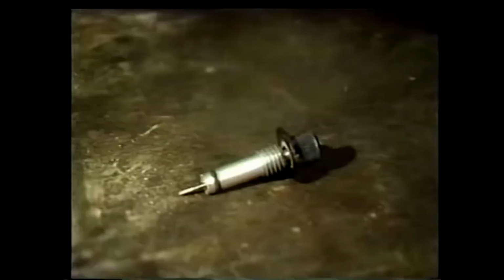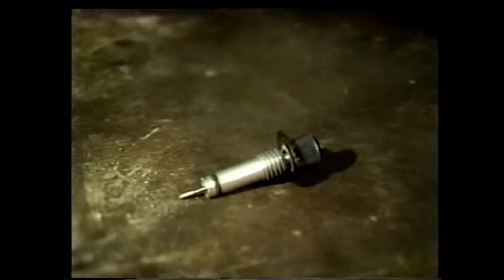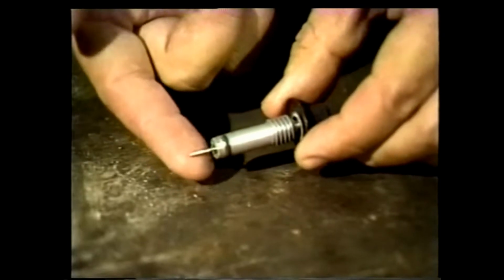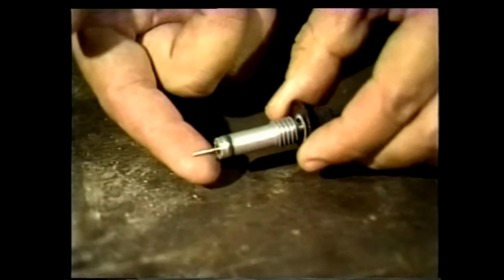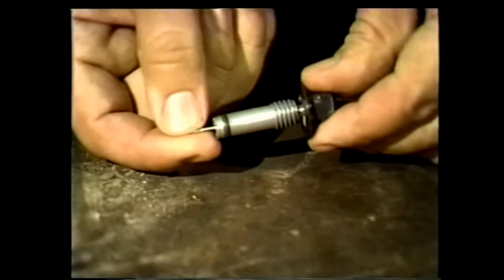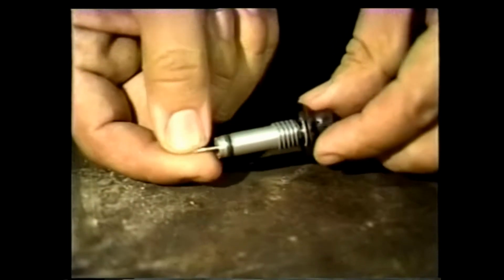The plug type disc has a wide seating surface. Now, this kind of globe valve enables excellent throttling characteristics for flow control. It can be used under all pressure and temperature conditions. This needle valve is a variation of a globe valve with a plug disc. Now, the plug goes well down into the opening formed by the seat. This gives the valve extremely good throttling ability.